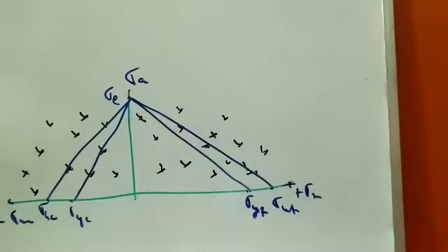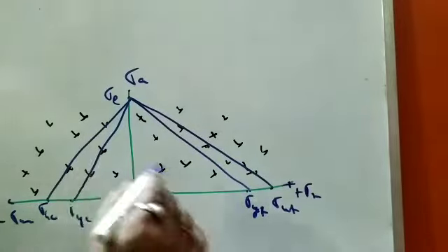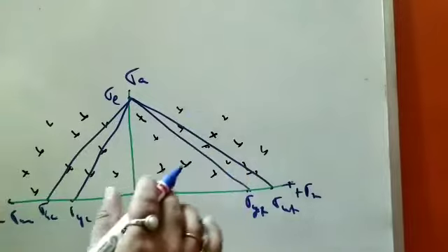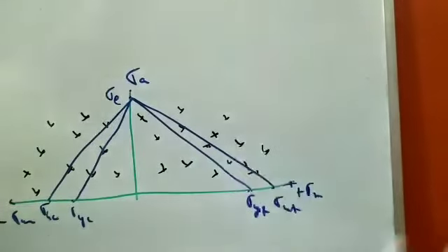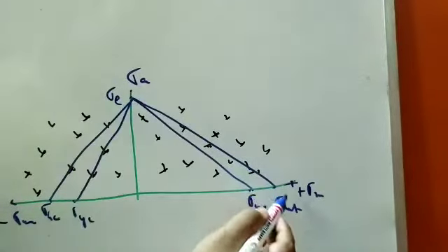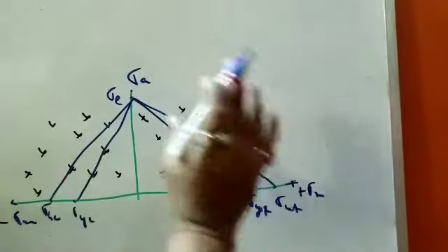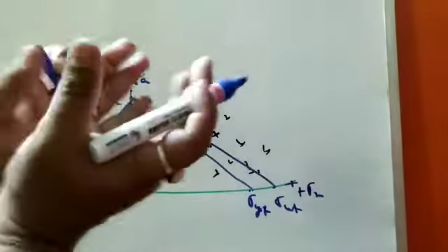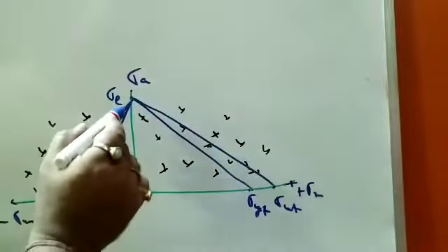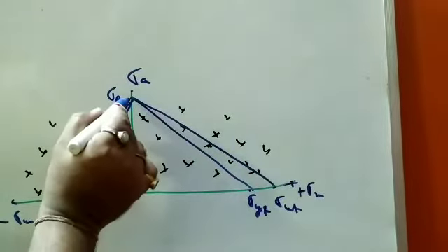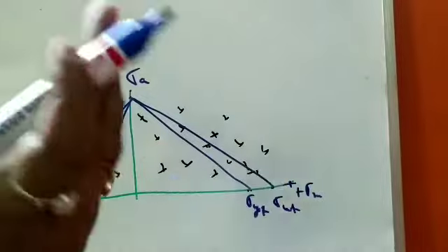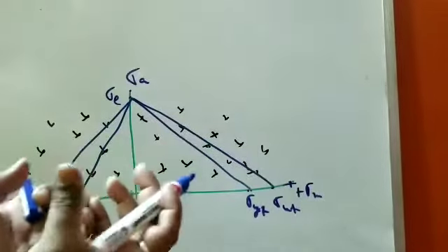We plot two lines. Now basically we see that when we plot these two lines, what happens? This is basically a curve fit. Some engineers thought that this line, joining from endurance strength to yield strength, takes many number of failure points.